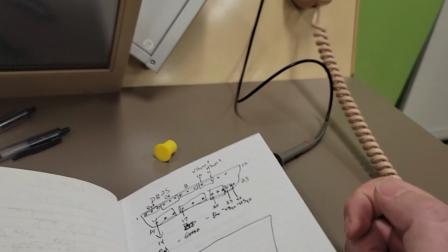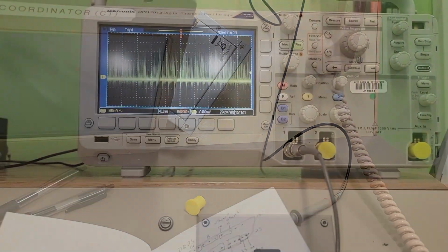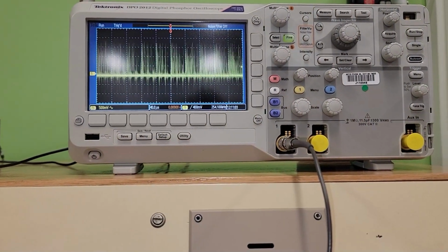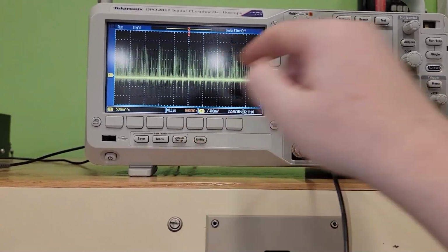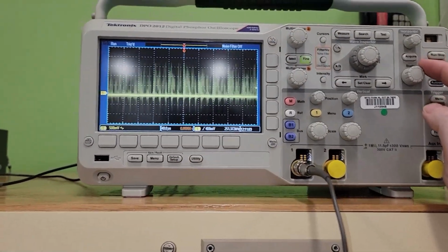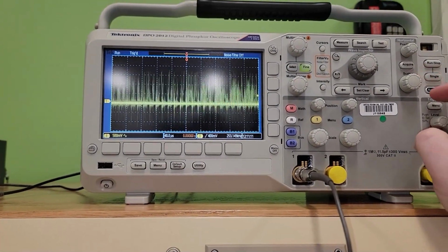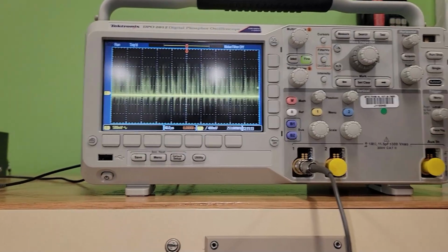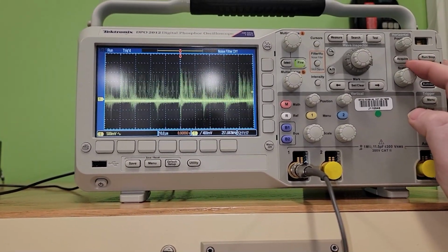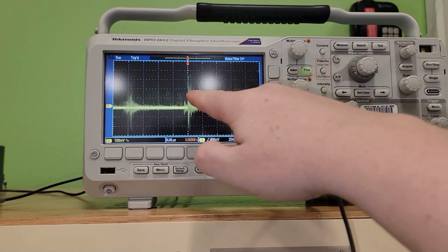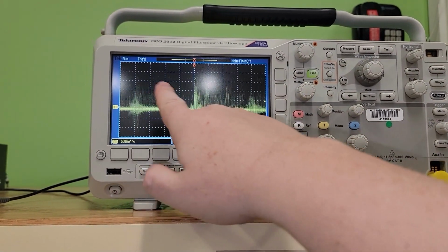So let's look at those signals underneath an oscilloscope. All right, let me first look at my red information coming on and off of one of the pins. You can choose 1, 2, 3. You can see that data sitting here. It's not really data per se. This is an analog signal. If I adjust my scale, we can break it down and see that information flow a little bit better, how this signal is repeating.